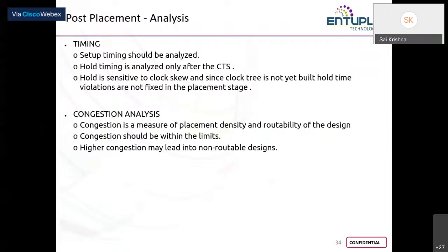So yeah, after placement, you first check for congestion and then your timing, area, power reports. In case you have any violation in your timing, you will optimize your design in such a way that the violation is fixed and there are no further left out.